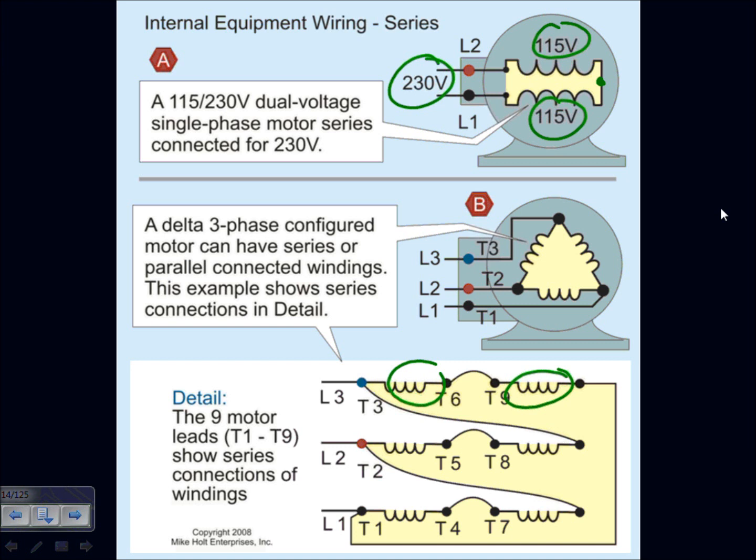And I know you guys touched on that one, but it's a very, very important concept, especially if you design something. You're not electricians, so to speak. But take this problem. I want you to design a 600 volt motor. No problem. And it can also run at 300 volt. No problem, Chad. I can design a coil that runs at 300 volt. By adding more coils, I can design 300 volt and another 300 volt, tie them together, and got you a 600 volt, right? And that will get you a 600-volt motor if you were to design a motor like this.